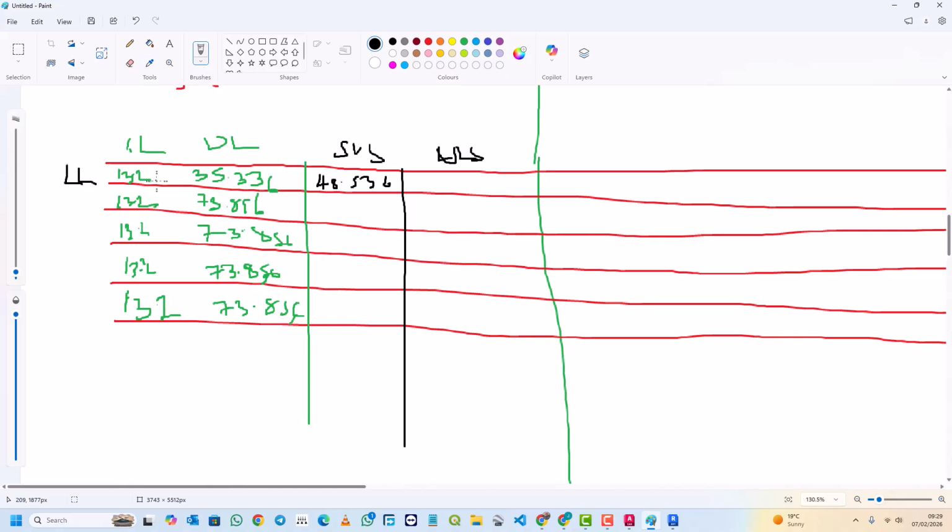So it will be in brackets 1.4 multiplied by dead load, which is this one, 5.336, I'm assuming that. Then plus live load 1.6 multiplied by 13.2. So this one will give me 70.59, like this. Now these two loads are very, very important. This one is for foundation design, this one for reinforcement design. So we will continue like this.